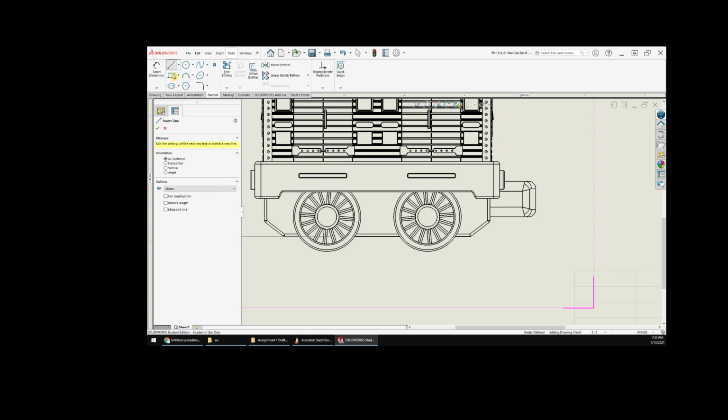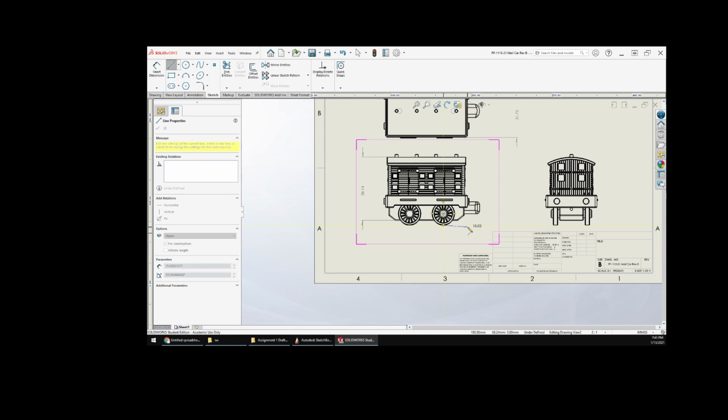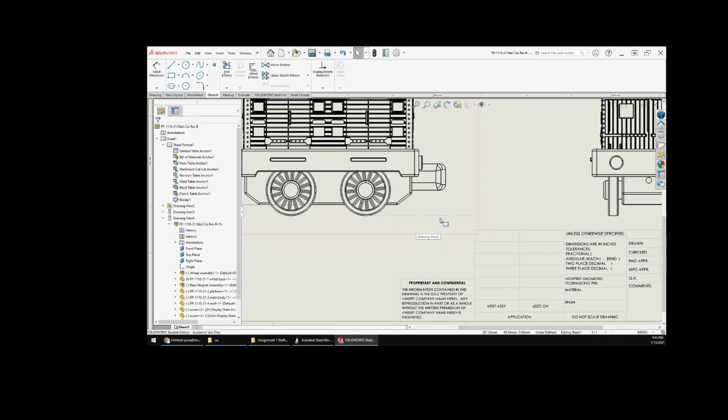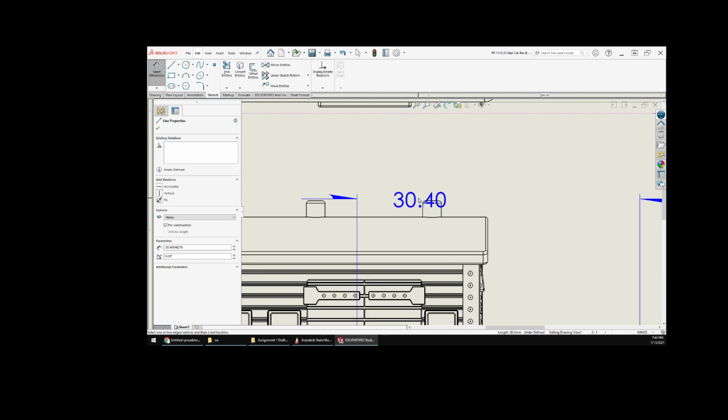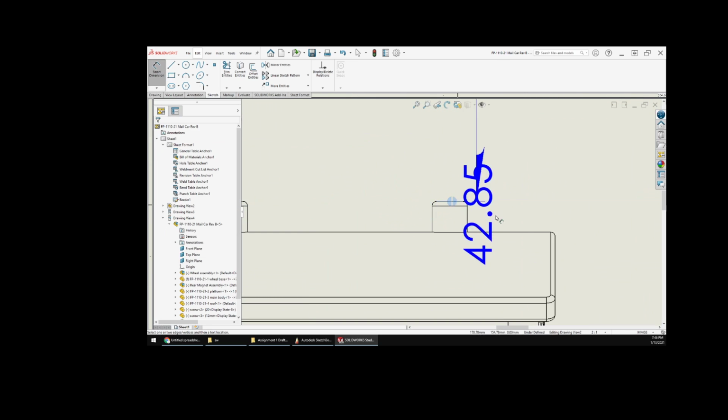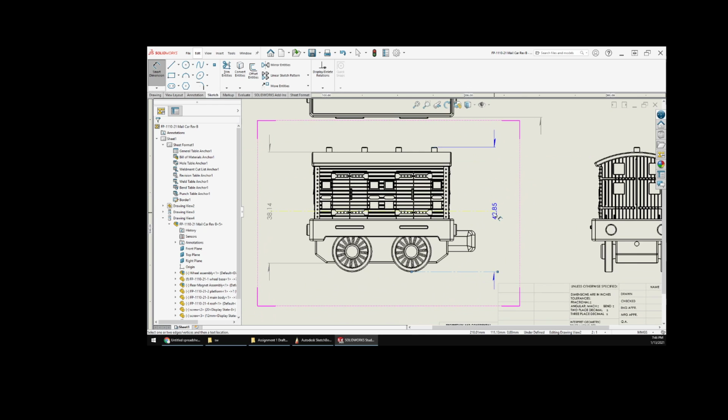This is where I would need to come in, draw a line, and you always want to do it as a center line, because a dashed line basically means it's not part of the actual object. And I want to snap to this, just so it gives me a point that'll allow me to snap to from a dimension standpoint. So now I can get an overall height here, and we're just going to go up to the tippy top, and go there.